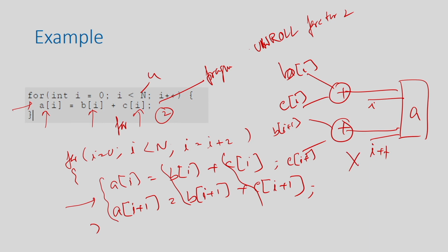So, if that particular block RAM is dual port, it is not a problem, because you can actually access 2 data, right. But if the unroll factor is 8, 10 or so on, in that case your dual port or single port does not help. So, how can I improve that? How can I make sure that even if I partially unroll and I am accessing more than 2 data of a particular array, I can actually achieve my required performance by doing the partitioning of the array? Okay. So, I will take a concrete example and I will show you how to do that.